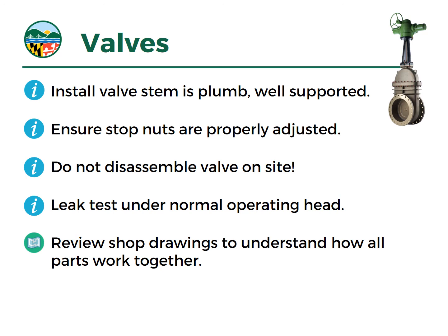time the owner went to close the gate valve, they weren't as familiar with the operation of the new valve. They kept on cranking and cracking, and they ripped the valve operator right out of the concrete because of all those forces that are applied to the concrete. But a properly adjusted stop nut would have prevented that from happening.